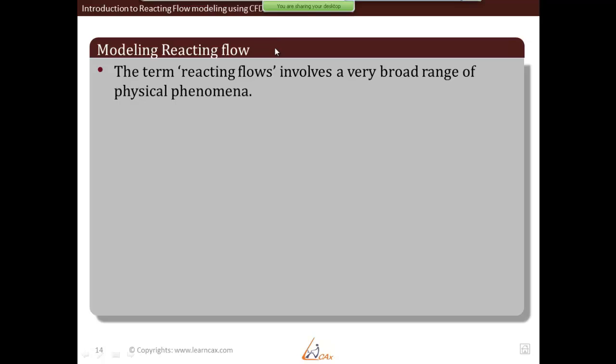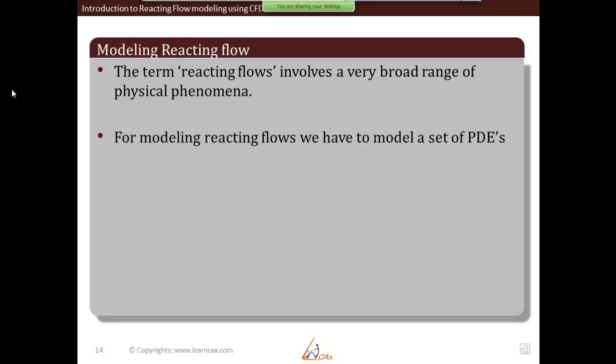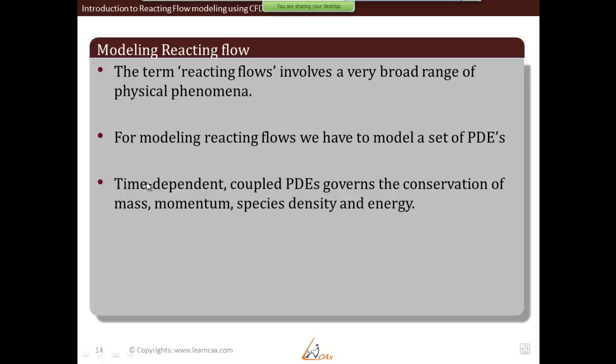Going back to our earlier discussions, since we have discussed concepts related to reactions, now we will move on and discuss some fundamental concepts related to reacting flows and the modeling approaches associated with reacting flows. When we say the term reacting flow, it involves a very broad range of physical phenomena, starting from chemistry up to turbulence and much deeper coupled physics. For modeling reacting flows, we have to model a set of partial differential equations. Those equations are time-dependent coupled partial differential equations which govern the conservation of mass, momentum, species density, and energy. All these phenomena are coupled together.